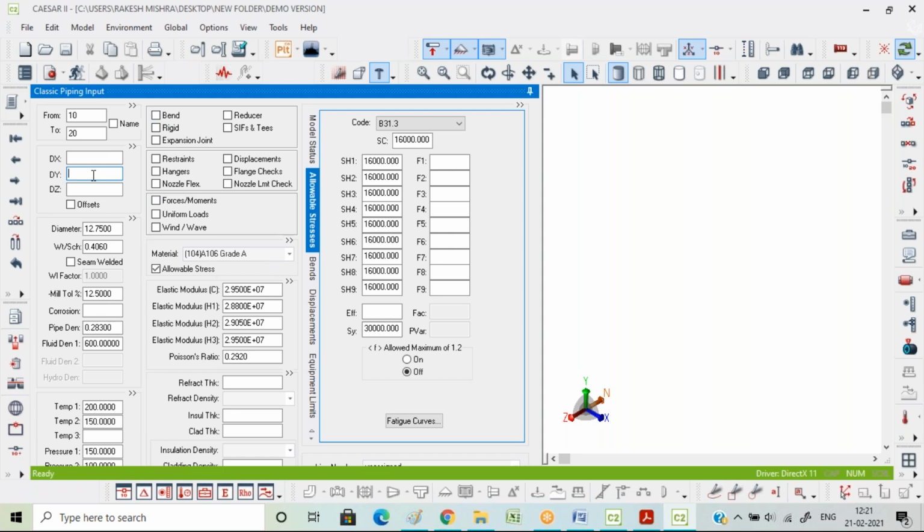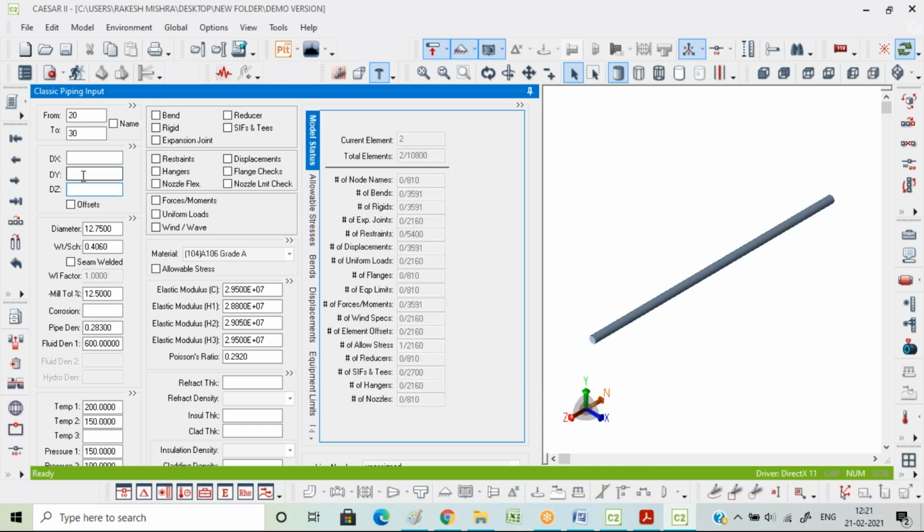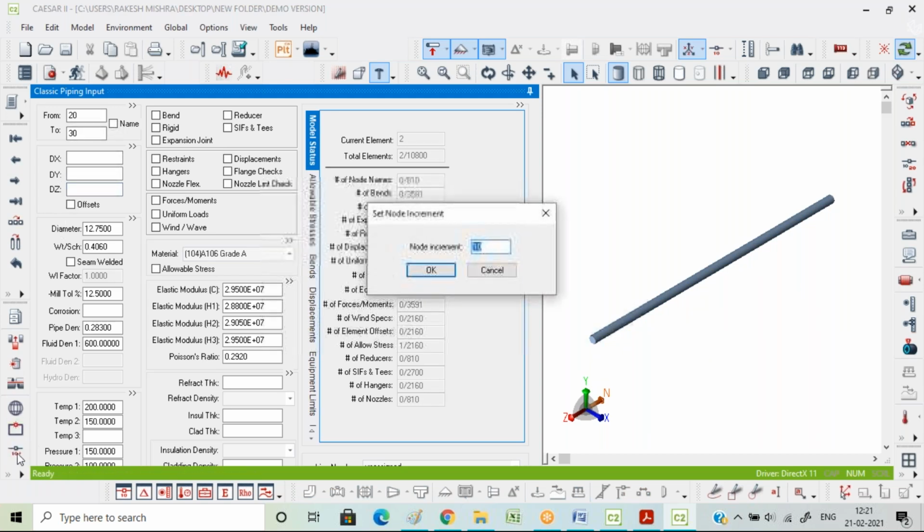We're wrapping it soon. So say we are supposed to design it. Now we're moving, say, 500 inches in this direction, and then we are coming downwards. For downwards, what shortcut are you supposed to use? It's Alt C to move to the next node. Now the default is that the nodes are taken with a count of 10. You can say the node increment is 10. You can even change it.